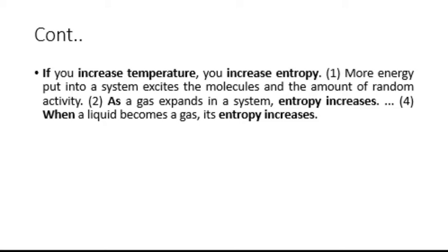When liquid becomes a gas, if your water is changing its state from water to steam, it is going into another state, it is taking heat from the outside, there will be a change in capital Q, that is nothing but the heat exchange. Its entropy is going to increase because randomness will be very high in gas as compared to liquid.